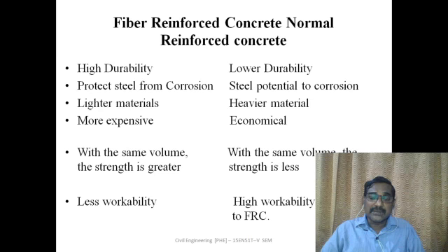So this is the comparison between fiber reinforced concrete and normal reinforced concrete. Fiber reinforced concrete has high durability, lighter material, more expensive, less workability, and having more strength for the same quantity of volume with respect to normal concrete.